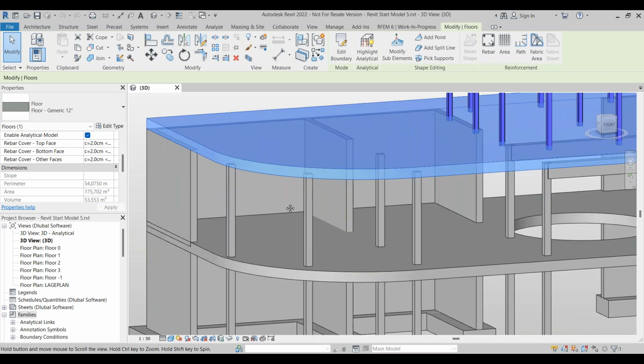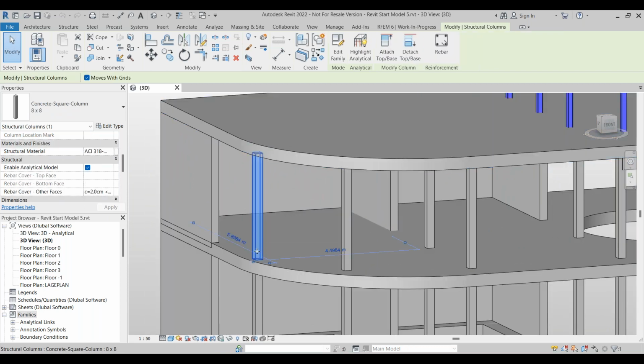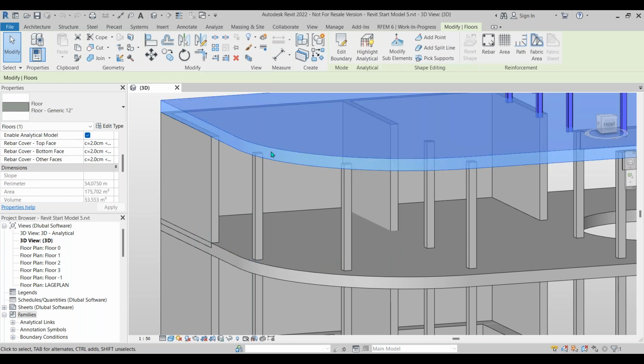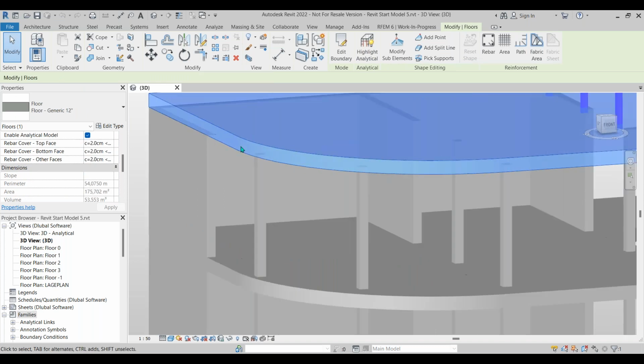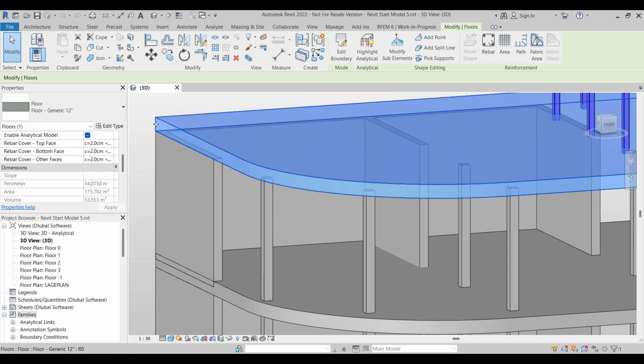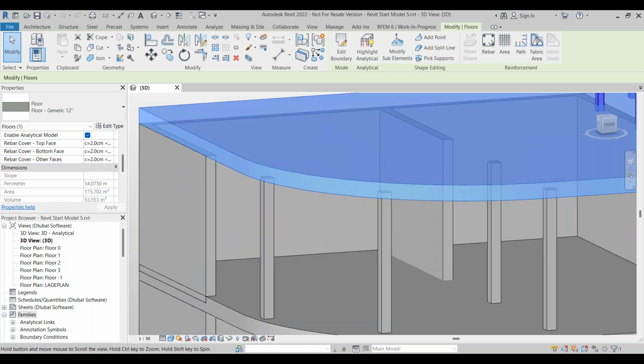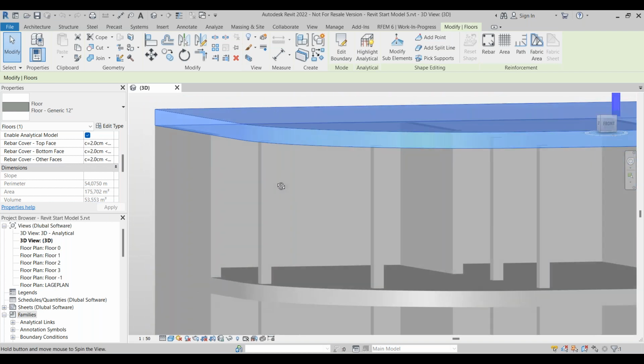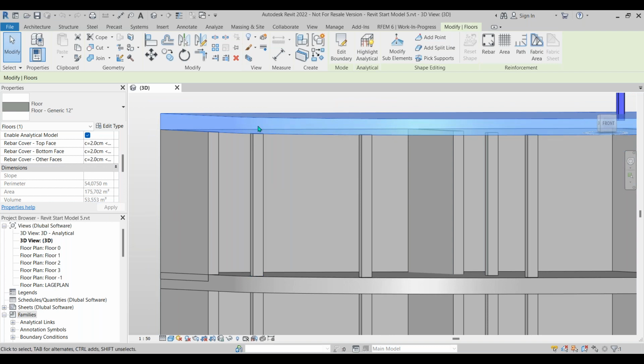And so if I'm converting my column, for example, into a simple center line that goes up the center of gravity of the column, and then a 2D object for my slab, which is going to go at the halfway point of the thickness, then naturally I'm going to have a gap that is going to appear between these two lines. And so what Revit is also doing is not only converting these objects into surfaces and lines, it's also connecting this gap afterwards.